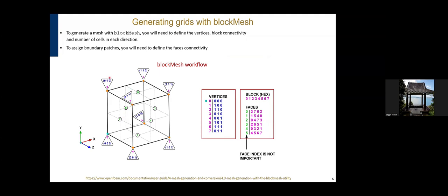Anyway, for generating grids in OpenFOAM, the first thing you do need is to specify the axis. So if you specify an axis of X, Y, Z this way, as shown here, then you have to begin to think about the vertices. What are the vertices, or the points, that you need to have? Because each cell is made up of points, and those cells make faces, and then the faces make a block. So you need to start thinking about the coordinates.